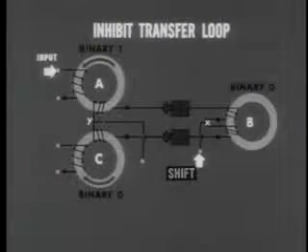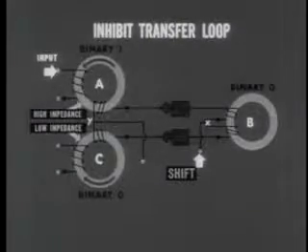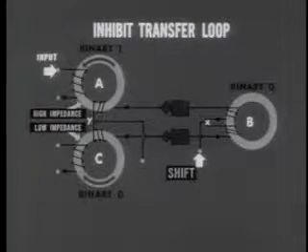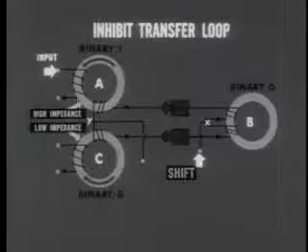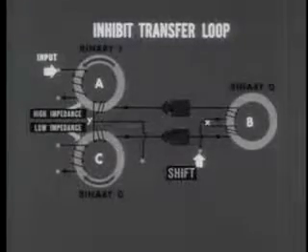A dot pulse entering the output winding of A will meet a high impedance, but the impedance at C will be low. Under the conditions we have here, the binary 1 in core A can be transferred to core B. When the shift pulse is applied, it divides unequally.